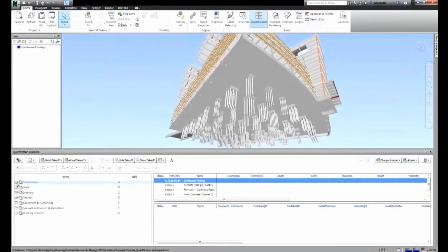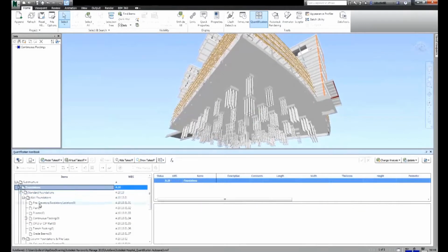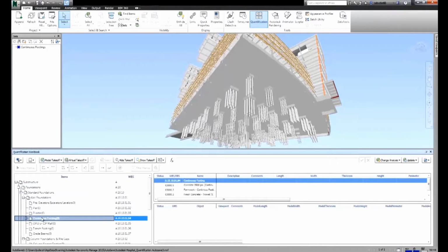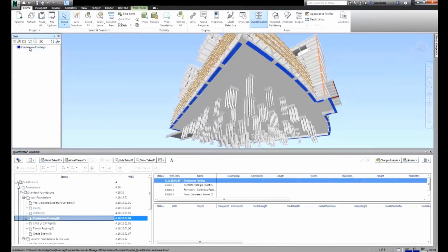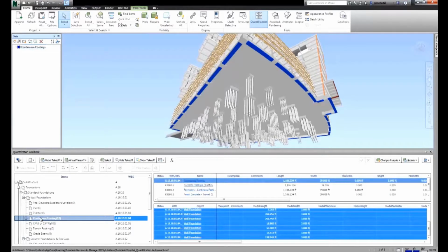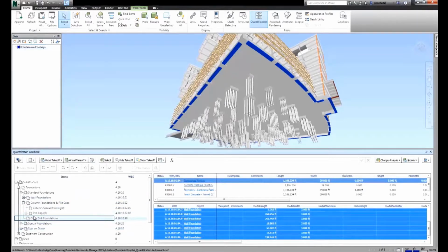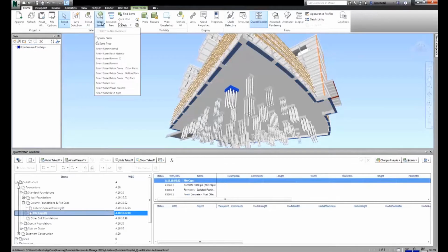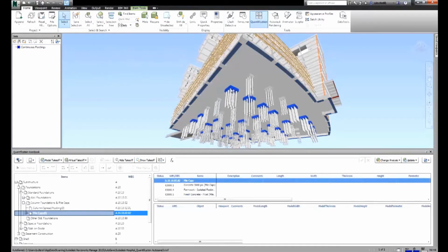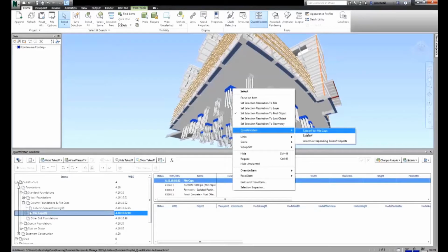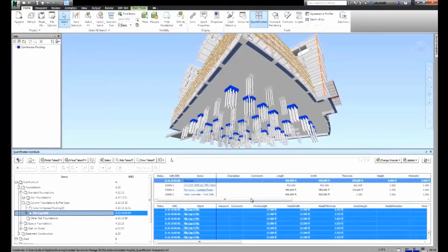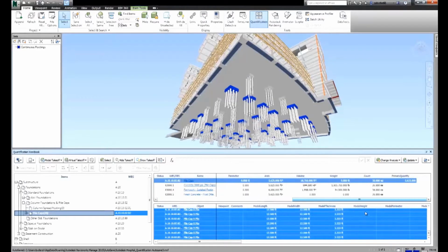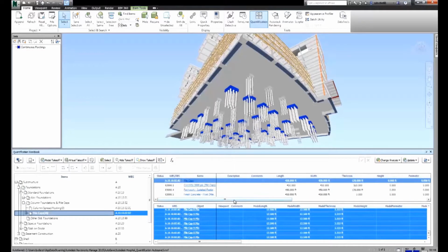Here we're seeing an item and resource catalog used to classify model elements further than the model ordering tools can. When the catalog is available, it is possible to quantify the model using intuitive tools in NavisWorks. Simply select an appropriate item within the catalog for quantification, then either drag and drop the elements from the model to the appropriate items. The workbook also leverages the item breakdown structures and the resource breakdown structures, and in that we can see a roll-up of the total quantities of an item collection with its resources.